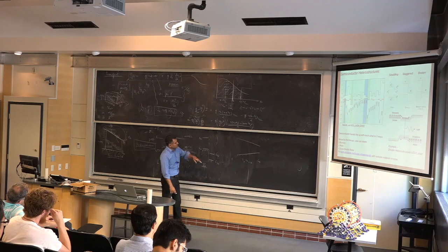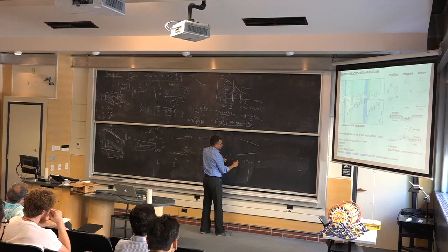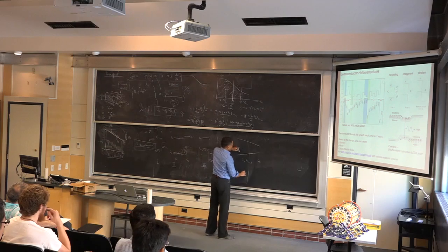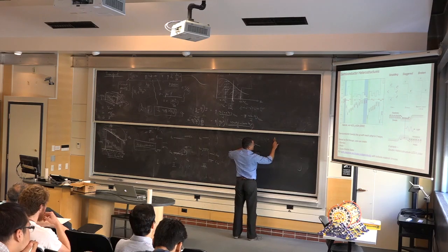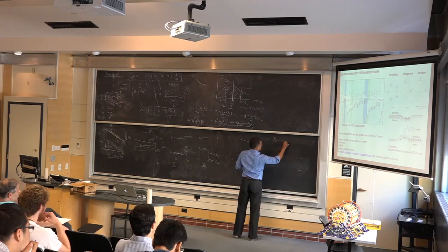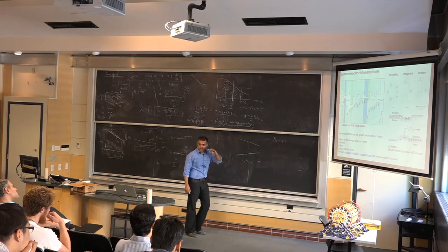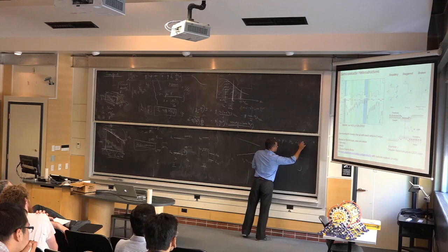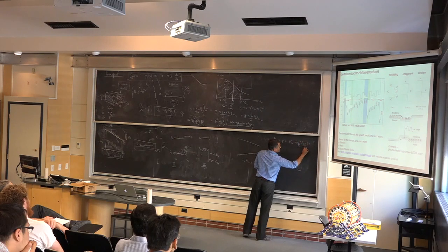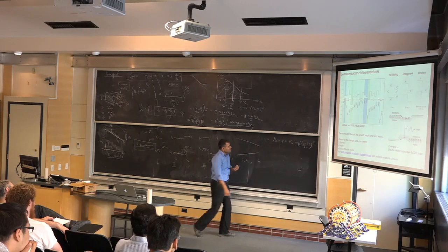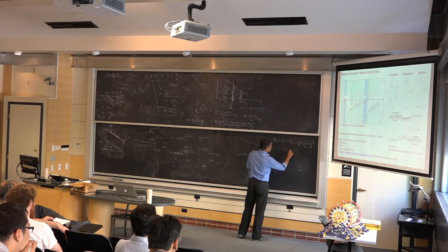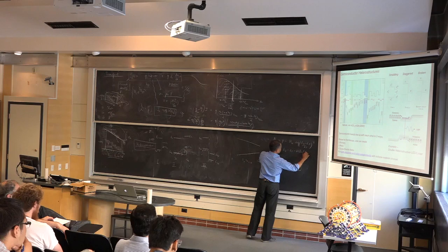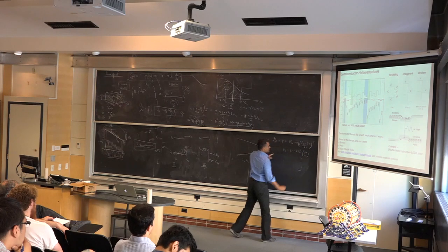Let's say I dope this whole region, the entire thickness of this layer, with p-type. If I dope it with p-type and do a relatively uniform doping, that will ensure the doping density NA becomes equal to p, the hole density, which will be roughly NV exponential of (EV minus EF) over kT. Does that make sense? So you can turn this around and say my valence band edge will therefore be EF minus kT natural log of NA over NV.